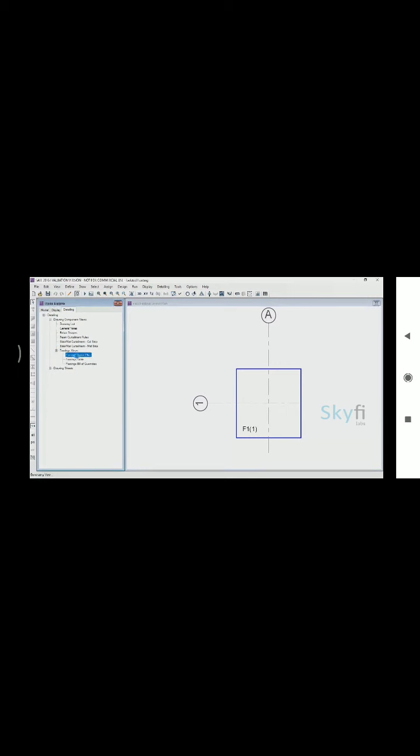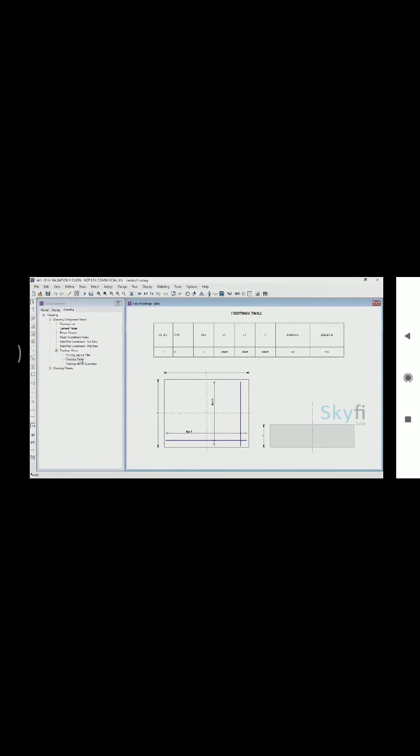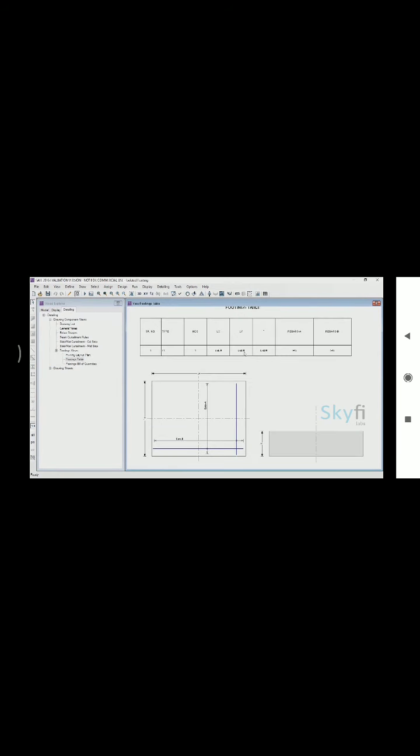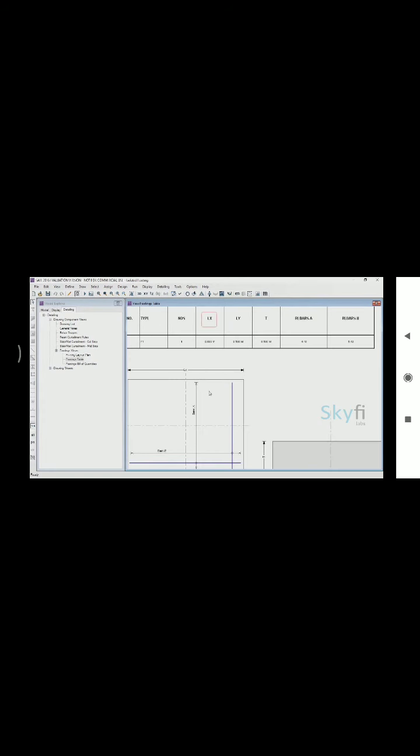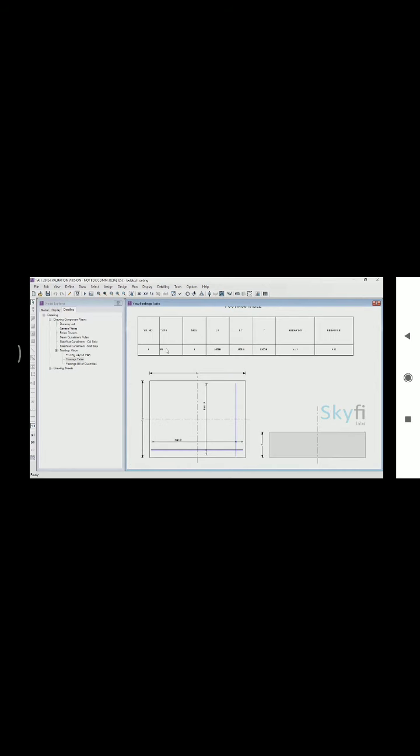The footing layout plan is already displayed by default. Next, select the Footings Table option. Zoom in to see the table clearly. The lengths in X and Y, as well as the thickness, is displayed. Next, the number of rebars in each direction is mentioned. Verify the directions A and B from the diagram below. Rebars A are the ones in the Y directions, and rebars B are in X direction. So, in A direction, there will be 4 bars of 12 mm diameter, and 5 bars of 12 mm diameter,